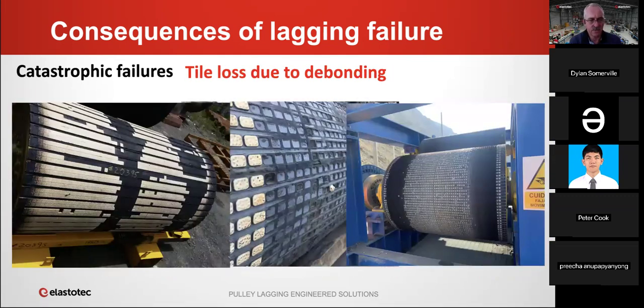The next catastrophic failure is ceramic tile loss, which can be a common problem with ceramic lagging. This type of failure is obviously bad for the lagging, but it can also be very bad for the belt cover because the missing tiles create uneven shear stresses and they can cause localized wear of the belt.